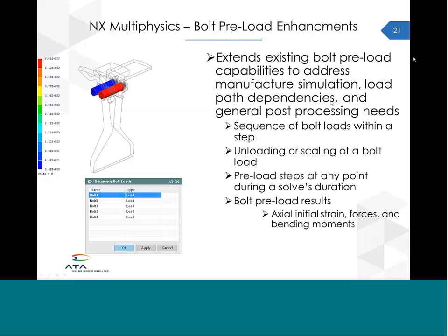There have been enhancements to the application of bolt preloads. Previously, bolt preloads were either enabled or disabled, and you either got all of the bolts in the model or none of them. Well, now there's a capability that allows you to progressively apply preloads to bolts individually, one at a time, or sequentially.